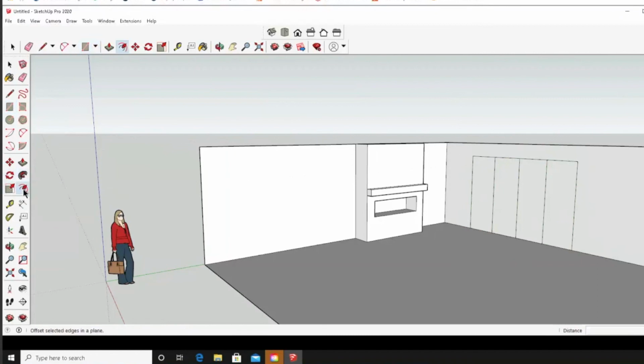The offset tool. We're going to click inside the rectangle and drag it in. So you see, I'm dragging it in. And again, don't click, but rather just type in 2, enter. So now I have a frame. Repeat. Pull it in. 2, enter. And so this is just a very simple, straightforward frame.